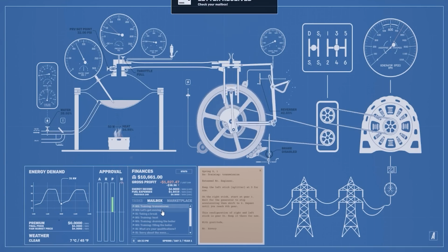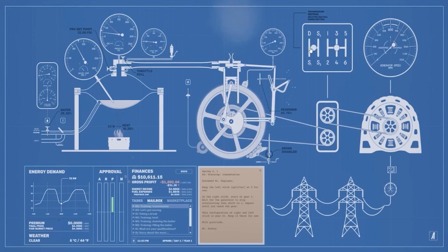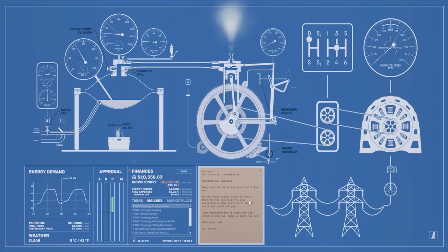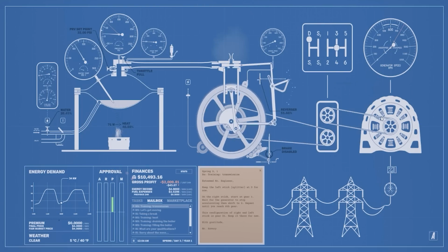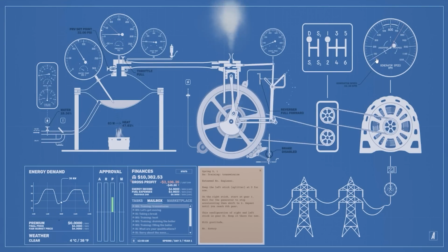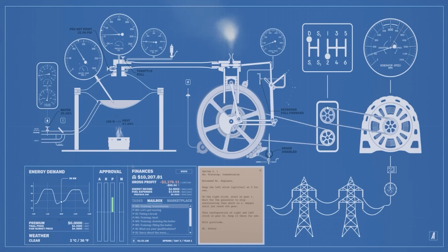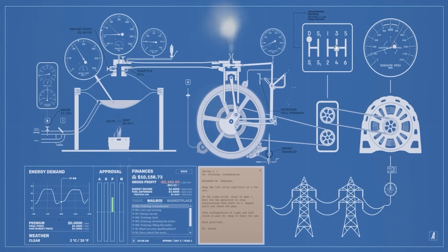Great. Transmission. Keep the left stick, the splitter, at D. That'll be direct, probably. On the right stick, start at gear 1. Wait for the generator to stop accelerating, then shift to 2. So this is where we've got our generator, the gearbox, and go 1. All right. So it needs to go, and then it needs to level out a little bit, which it sort of is. Then 2. Okay. Then 3.